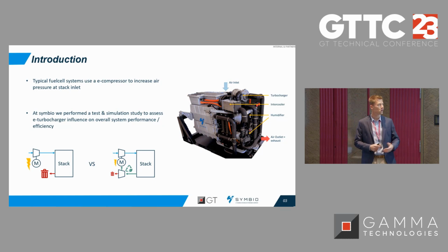The two main advantages of the turbocharger compared to the E-compressor are to recover some energy from the exhaust gas, so we will reduce the electric consumption of the compressor, and to increase the overall pressure of the system to increase the efficiency of the stack itself.